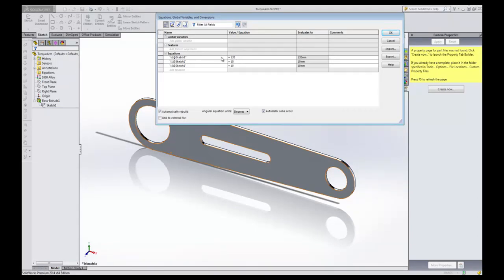The last thing I want to mention is that there are certain responses that can be exported automatically from SolidWorks. One of them is the mass properties, which is automatically read by HEEDS, provided that I have a material assigned to the model. Here you can see the model is made from 1060 alloy, as defined there.